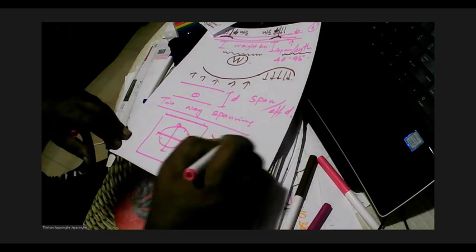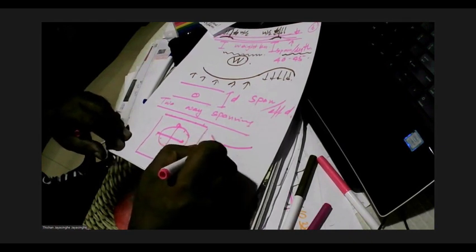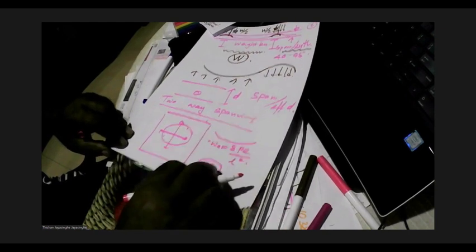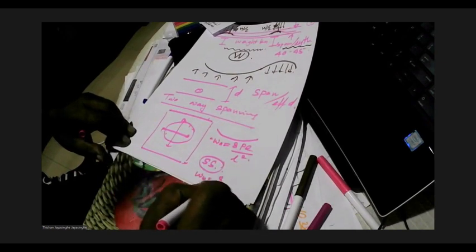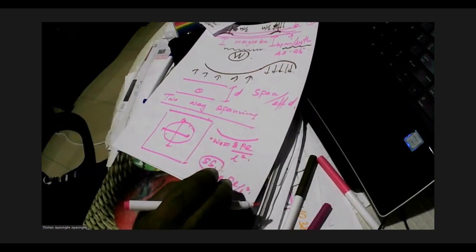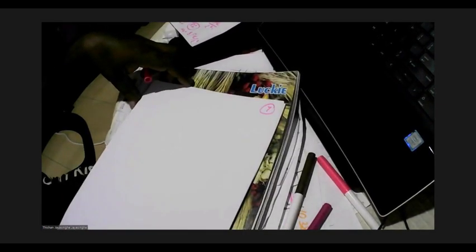And when it's spanning this way, you can say WA is equal to 8 PE over S squared. In the other direction, you get WB equal to 8 PE over S squared. So you might have 60% of the load carried in the short span direction, 40% carried in the long span direction. We really don't know. So the moment you get uncertainty, we have to think about it carefully. We really don't know how much load will be carried in each direction.